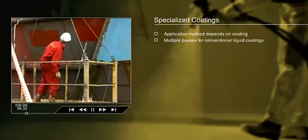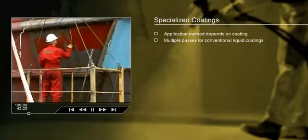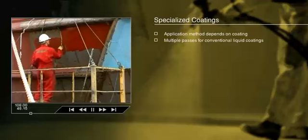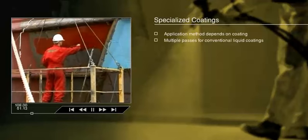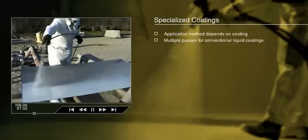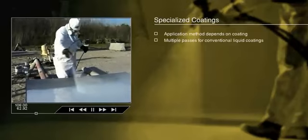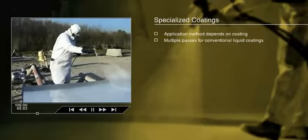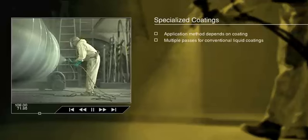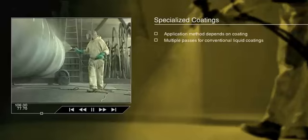Conventional liquid coatings, applied by brush, roller or spray, should generally be applied in multiple passes, thin enough to allow proper evaporation of the solvents as the coating dries and cures. Some high-build coatings, particularly those with thixotropic qualities, dry too fast to allow reworking that would occur with brush application and must be sprayed. Other high-build coatings cannot tolerate the thinning that would be necessary to make them pass through conventional spray equipment, and airless spray equipment must be used.